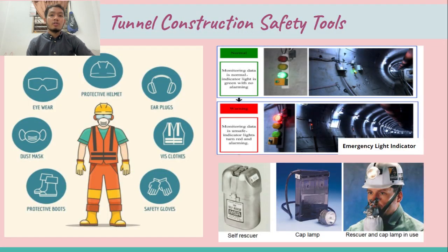So for tunnel construction safety tools, the workers must wear PPE. PPE is such as protective boots, dust mask, eyewear, protective helmet, earplugs, and safety gloves. Next, the emergency light indicator can also be categorized as a safety tool. This functions to give an alarm to the workers during construction inside the tunnel. Another safety tool is the cap lamp.